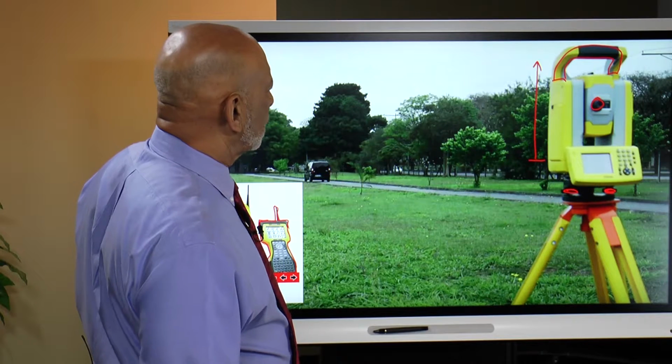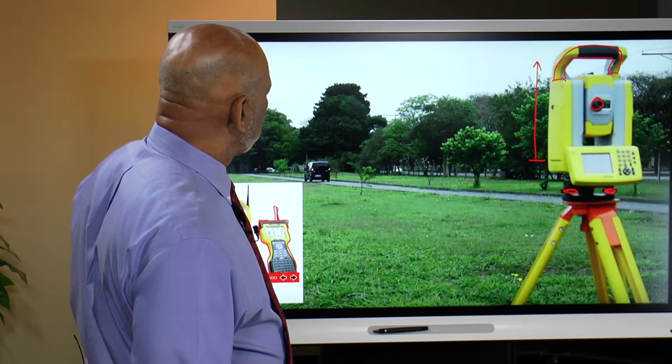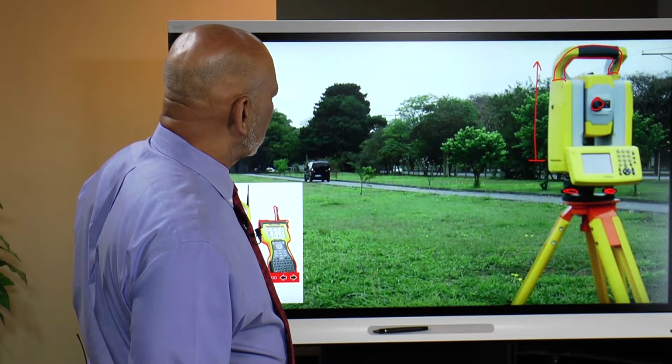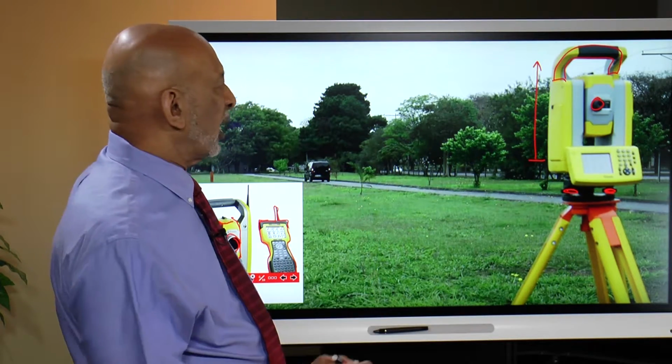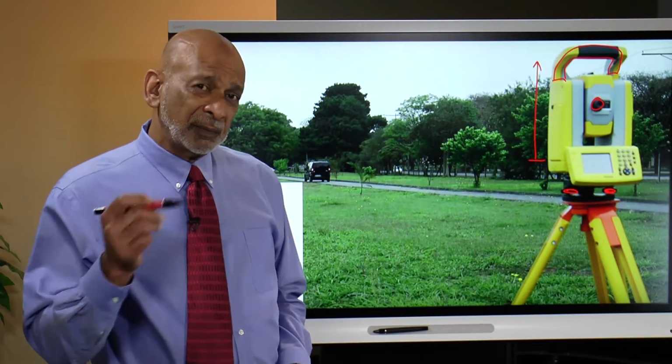Once we get to these total stations, people had discovered in the older technology, the theodolite technology, ways of using gravity in a similar way to the way you use gravity in an automatic level, to be able to detect gravity and apply that known direction in some fashion to the vertical angle reading system to improve the accuracy of the angles measured in the vertical plane.